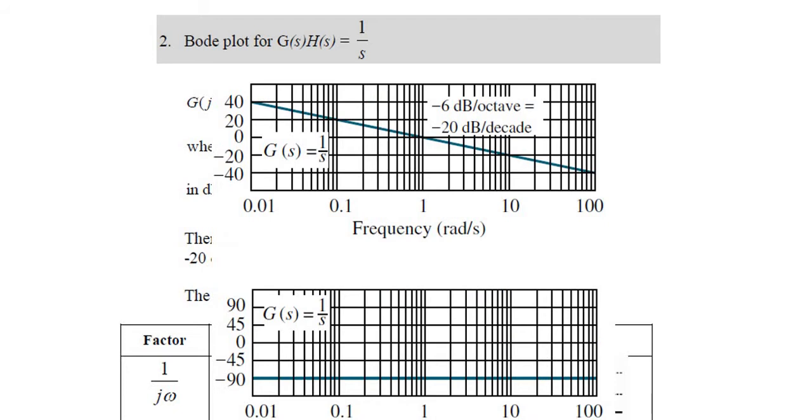In terms of the semilog paper, you can see that the same thing happens here. The intersection is at 1. In order for you to have minus 20 dB, from this side you have 0 to 20. Make sure that for the scale, you have 20 here and 1 here, so you just make a line here, and then you can draw the whole line there. So you will have minus 20 dB. Remember that 1 over S is minus 20 dB. And for the phase, you will have minus 90 degrees.